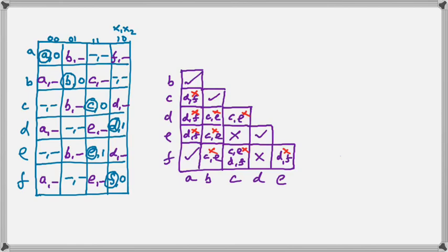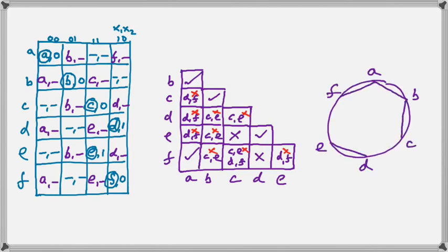So we take now the compatible squares. As you can see, there are only 4 that have ticks, and we put them onto a merger diagram. And our merger diagram shows that there are no geometric forms, so we cannot really combine any more than 2 states. So therefore, our compatibles are going to be AB, BC, DE, and FA, and those rows we may merge.